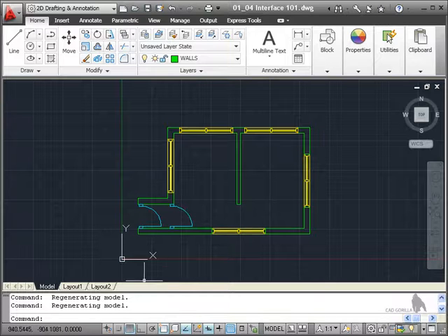Right down at the bottom of the screen, we have the status bar with coordinates and our drafting settings. Notice when they're highlighted in blue, they're on. When they're not highlighted in blue, like the dynamic input I've just turned off, it's switched off. Click again, toggles it back on again. Here you also have some other tools such as annotative scale, and also here you've got workspaces again and various other settings that you can utilize to basically tidy up and work with your AutoCAD user interface.